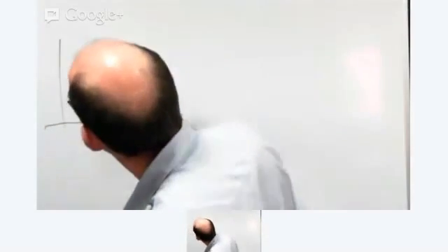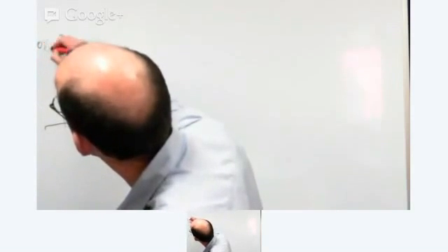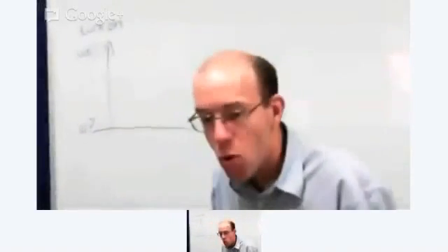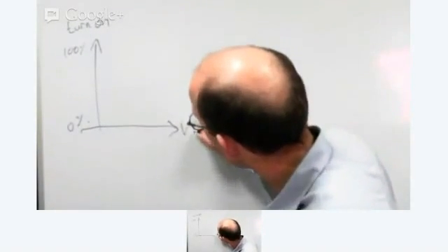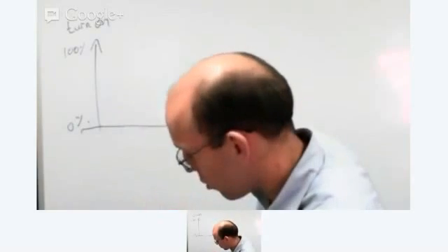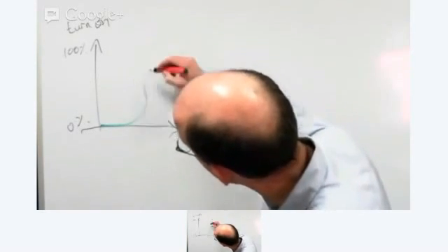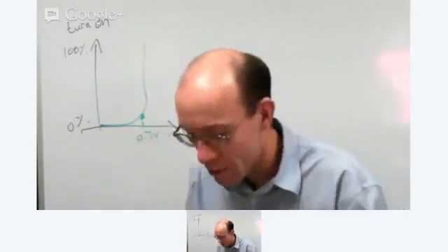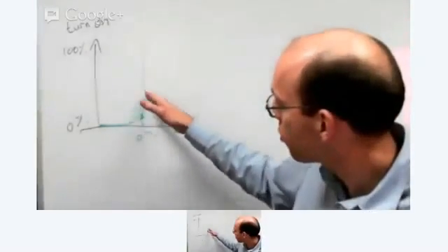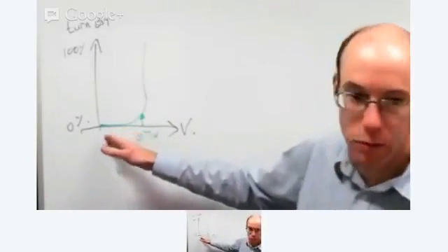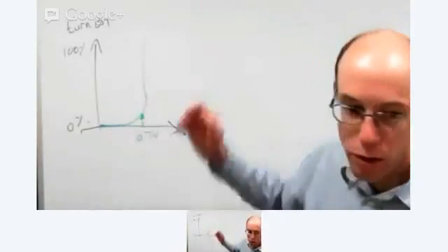So if I was to draw a graph and we put 100% turned on up here, and 0% down here, what we'll find is that as we increase the voltage, it's completely turned off at the bottom here, and as that voltage increases, it then starts to turn on, and then it'll switch on to 100%, and this point here, that's the 0.7 volts that we're talking about. So it's not exactly 0.7, but it will switch on around there. So it doesn't go quite from being off to on instantly, but if we switch it from 0 volts to whatever the power rail is, it will switch on.